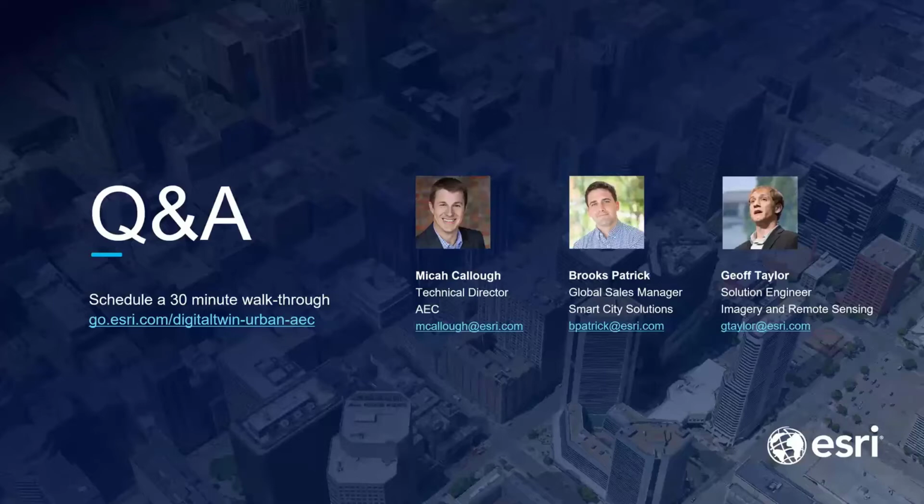So the first question was more related to BIM and facilities. I'm going to scan my building. I might have a SLAM scanner, a standalone scanner, something else. Most of the scanners, if they're really good, get about 2 centimeters accuracy. Typically, you can even decimate, which is to reduce the point numbers in that scan before you work with it. So if you're creating your digital twin from an interior scan, you would take it into Revit to be able to process it in BIM, for example, for your models to be used in that whole AEC workspace.